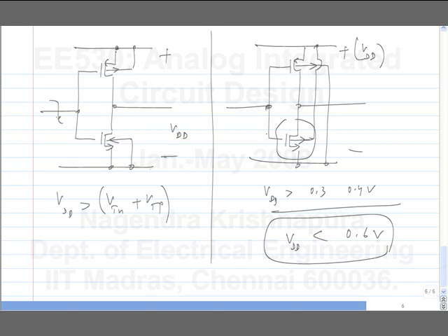And also there is another thing. If you have gone through a basic digital course, do you know what latch-up is? Latch-up happens because of forward bias junctions in the substrate, right? So there is another risk also. Now with modern technology where you isolate the different transistors differently, they say that there is not much risk of latch-up. The doping of the substrate has been increasing to reduce the risk of latch-up. When you increase the doping of the substrate, there will be very little voltage drop across different points in the substrate. So what happens with latch-up is you will get a positive feedback structure like this.